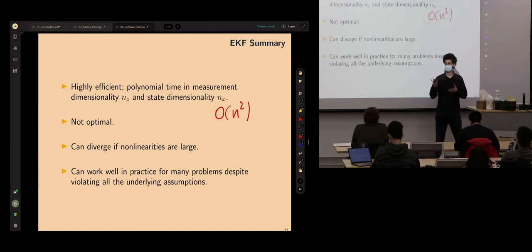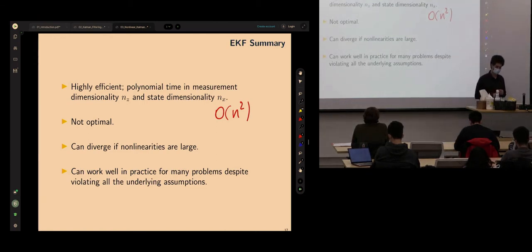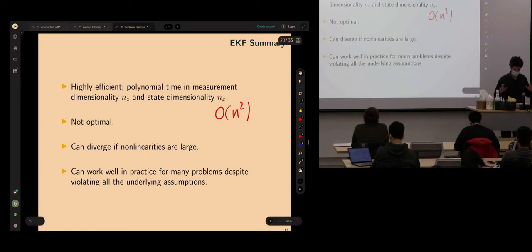And because the Kalman filter and linear least squares are the same, that's one way to show it. We did not go through that. If you're interested, that's a good conversation to have, maybe on Piazza or office hours. But to clarify, the question is, how can we show that the Kalman filter is the optimal linear filter? Then we need to look into proofs for the class of estimators that this filter tries to compete with. But the topic is BLUE, best linear unbiased estimator.